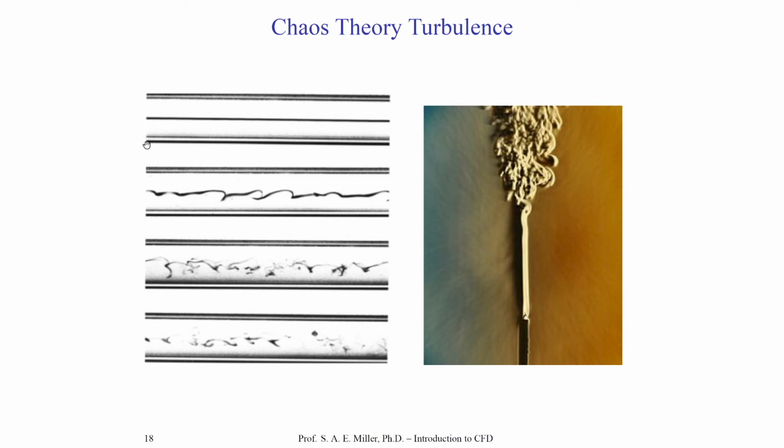This is illustrated on the left. This is the transitional problem. So you might see initially we have a laminar flow which transitions and becomes fully turbulent. This is an example where the solution is almost uniform and stable in the beginning part of the flow, and as time progresses, that is, the front of this turbulence is convecting upstream, it develops instabilities. And of course, you see this is fully turbulent.